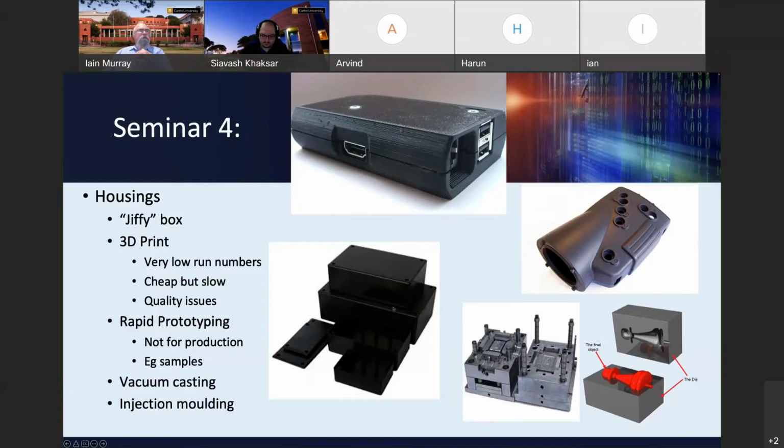Another couple is vacuum casting, and luckily I have here something that is vacuum cast. This is actually a raspberry plant, but the container, and if you look at most pots that you get from a nursery, are vacuum formed, usually produced in very, very thin material, so that you heat it up and when the vacuum forms, it draws it down correctly. But again, very, very weak.